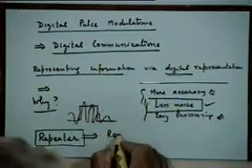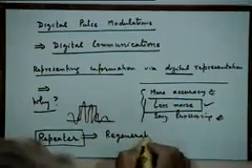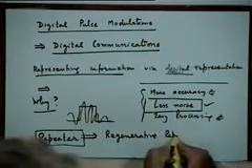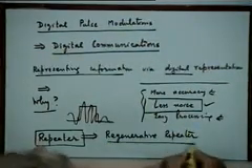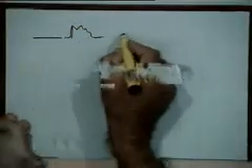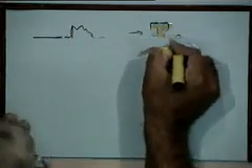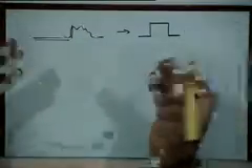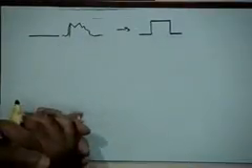So a repeater here would have to be of a special kind. It will have to be what is called a regenerative repeater, in the sense that you have to clean up the pulse and transmit a fresh, absolutely clean pulse once again. As the signal is propagated, it becomes a little noisy on the way. So the pulse looks like that, and you clean up this pulse and convert it into a pulse like that by very simple clipping and matched filtering kind of operations, and then retransmit it and keep doing this regeneration as and when required.